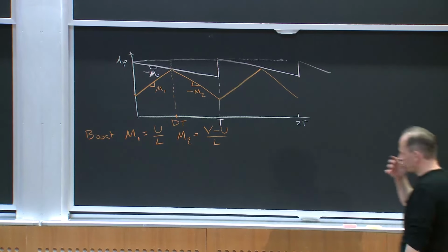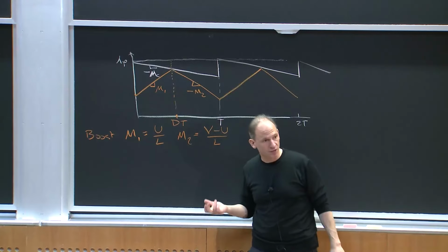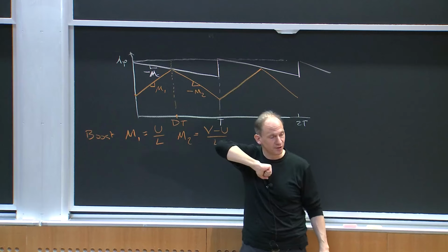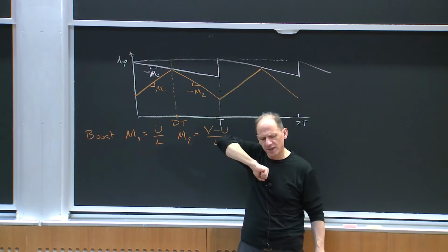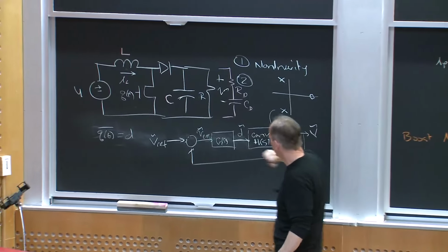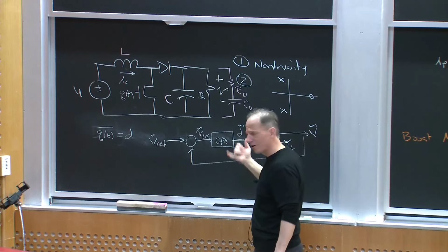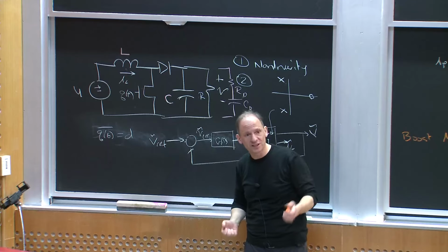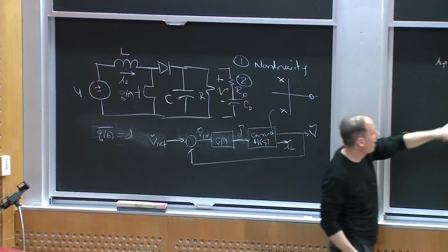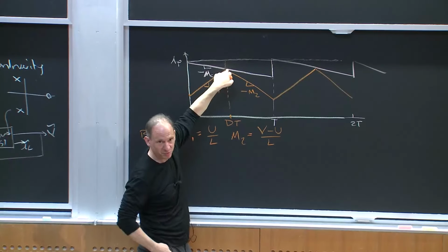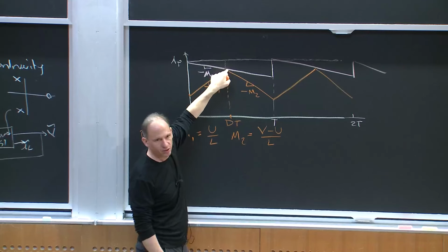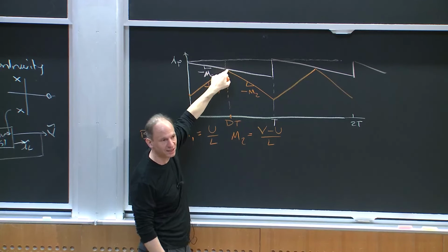So why am I doing this? Well, a couple reasons. One, we're going to see it gives us much nicer dynamics. Why? Because I'm basically explicitly controlling the inductor current. And then the other thing that's kind of nice is if I did duty ratio control, okay, you know, what is the inductor current doing? I don't know. If I put a small resistance on it, it's just going to keep cranking up the current until it does what it wants, right? Here, I'm telling the switch to turn off if the current gets too big. So this sort of gives me automatic current control. My currents can't get out of control.